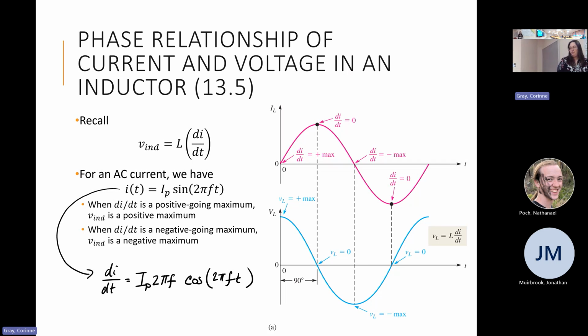If we take the peak current, two pi, multiplied by the frequency, then we multiply it by the inductance value, because that is part of the equation there, that gets us a volt. A lot of weird unit stuff happens in that, but if we're taking this derivative, multiplied by that inductance, just trust yourself that it pops out in volts. If frequency is in hertz and inductance is in Henry, that works; if you have mixed units, you would have to think about what's going on.